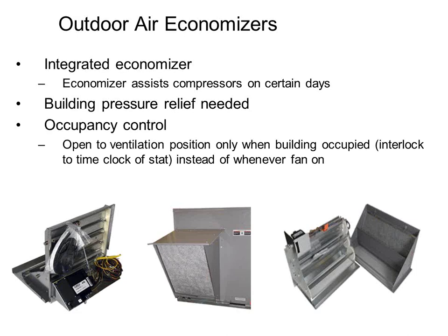building pressure sensors. I definitely want to get a thermostat that has that occupancy contact that I mentioned a few minutes ago, and then wire that occupancy contact to the economizer controller on the rooftop. All the modern economizer controllers have an input waiting for that, right? So if I get the right thermostat that has the output, and I have an economizer that has the input, I just need to get the wires from point A to point B, and I can make that happen.